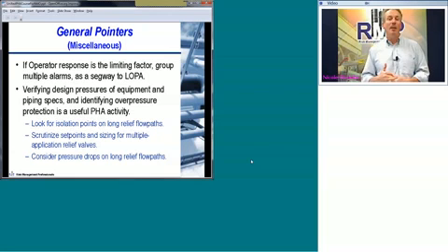Multiple alarms can be good if they're contributory towards diagnosing the event and not clouding the issue. It can be bad if they're not properly prioritized and there are so many different things going on that the operator has trouble diagnosing what's happening and taking corrective action. So any way you slice it, it's a single operator action, and that segues into LOPA because they only give you 1 credit for operator response using 1 or multiple alarms.